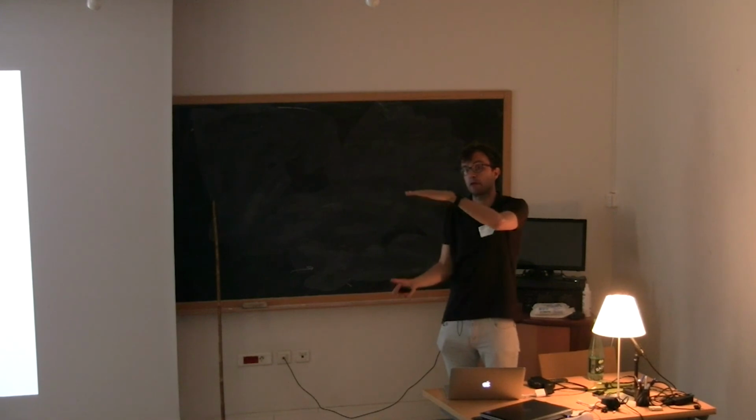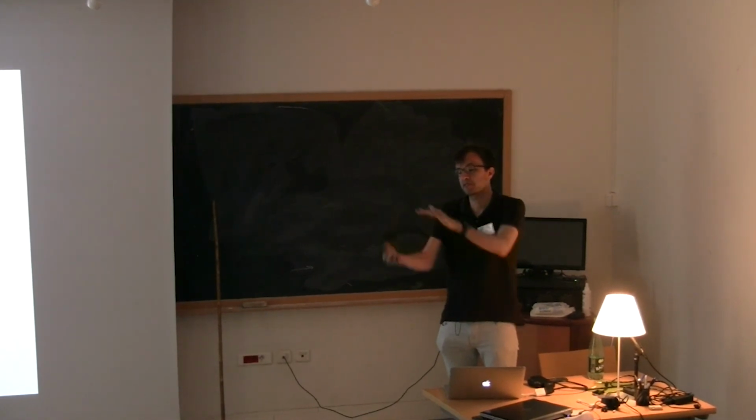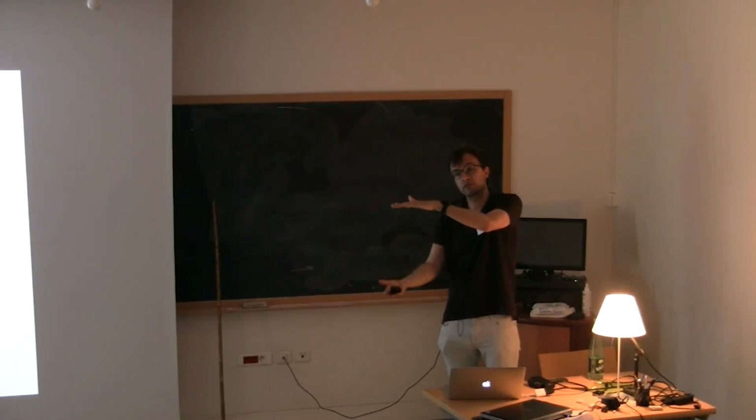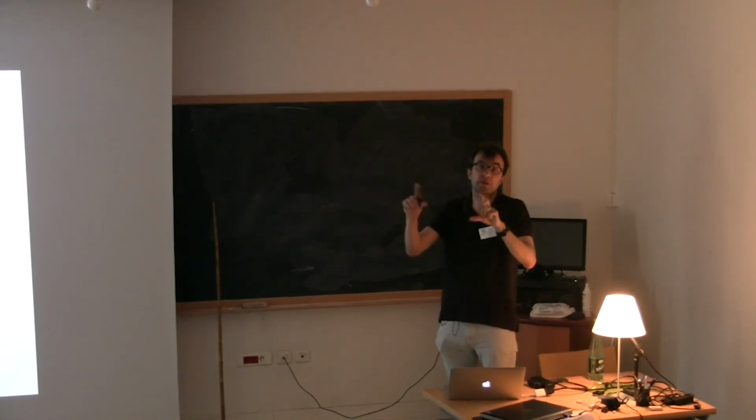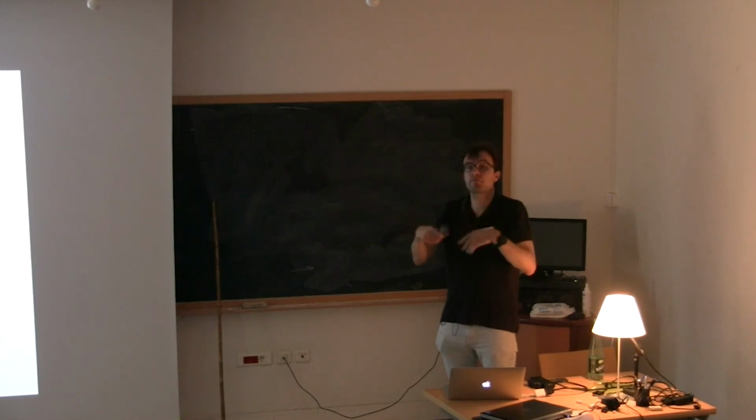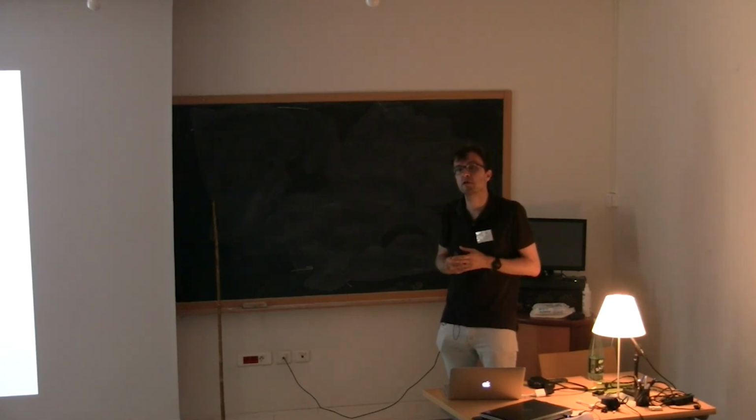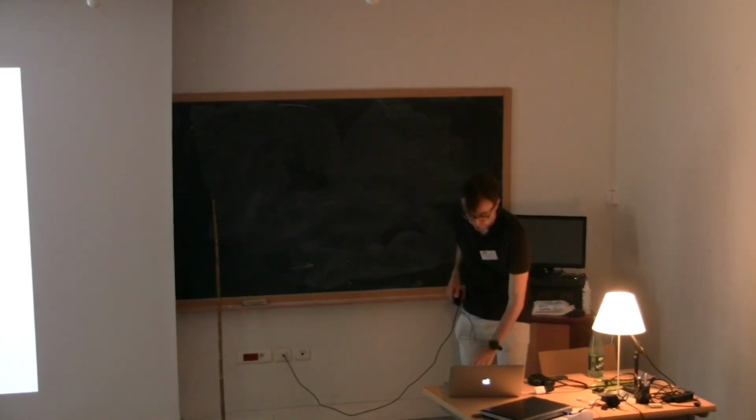So if you have a 10-meter depth that you're interested in, and you want a survey where you have information about every 25 centimeters or so, a few thousand measurements, that will take you 1 or 2 hours. So it's pretty quick.